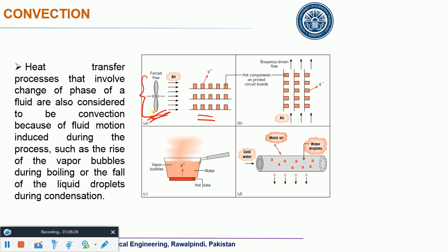If your fan stops, heat transfer rate would be very low, and in that case your computer may burn down. Just like the case for your automobile as well. You might have seen the fan. If your fan stops, the engine may seize, isn't it? Why? Because it would not be able to keep extracting the heat, and your engine would not be having proper heat transfer from its inner surface, and then the heat may go up to a level where it can seize the engine.